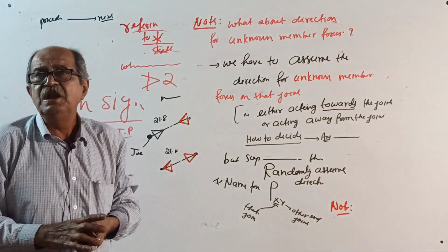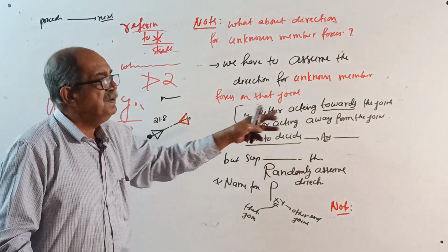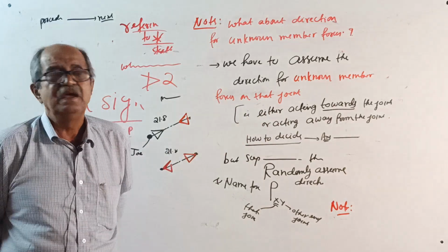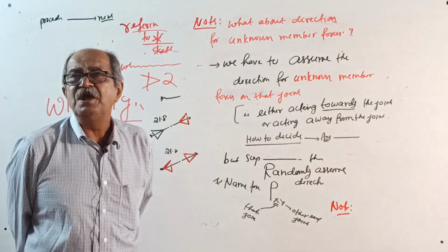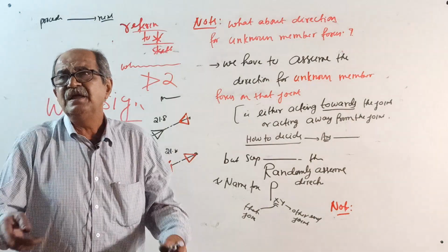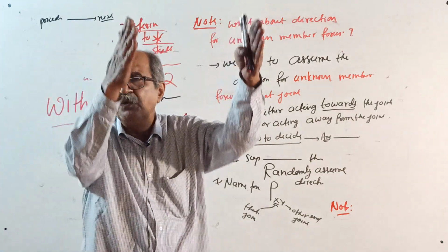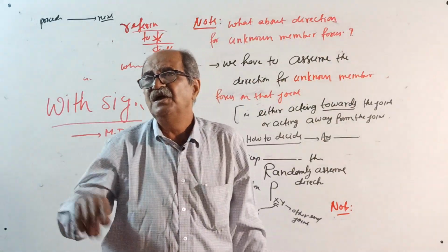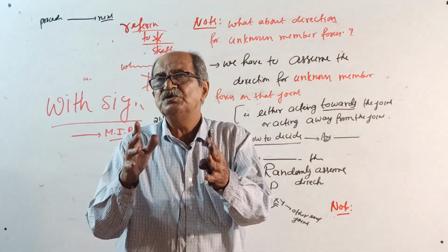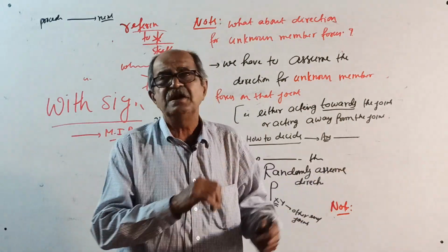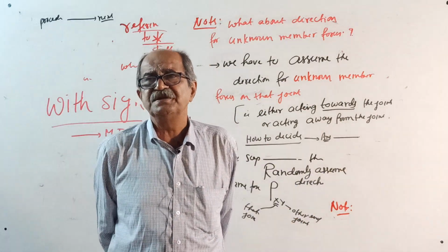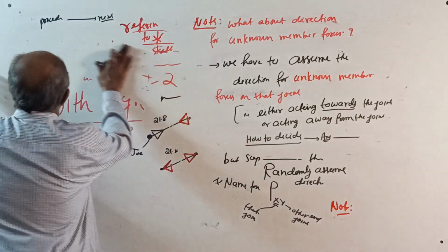This you do till you get perfection. Complete the procedure. Then, if they ask for tabulation, you prepare member, force, nature: member name, force, write the value. Nature means either tension or compression.